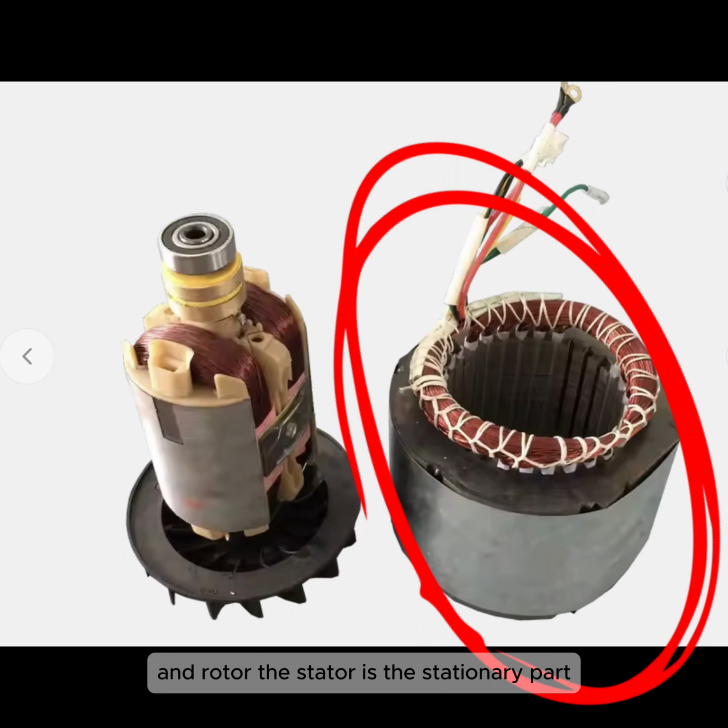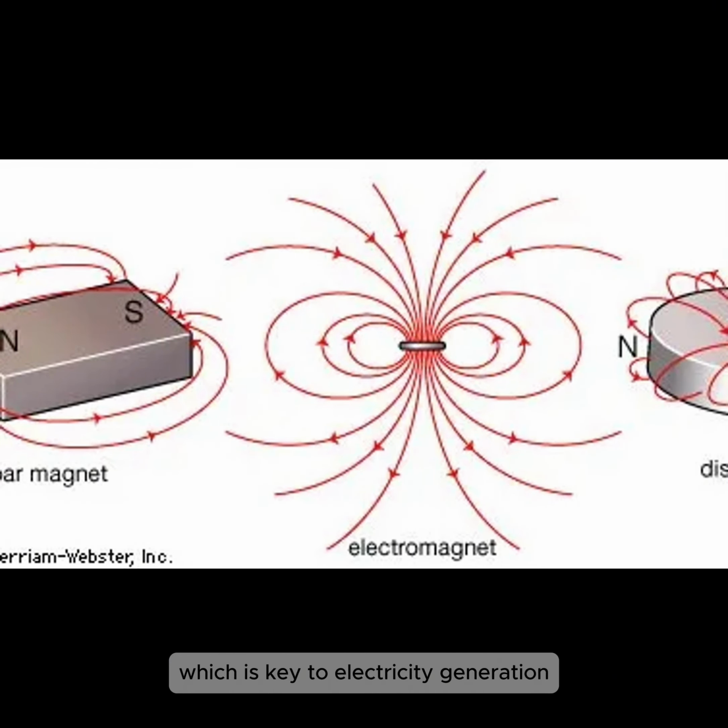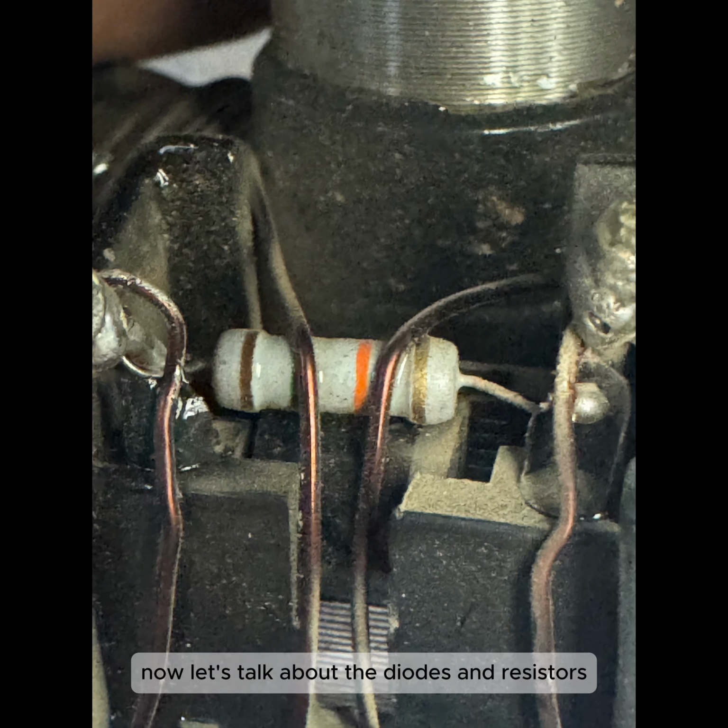The stator is the stationary part, while the rotor spins inside the stator, creating a magnetic field, which is key to electricity generation. Now, let's talk about the diodes and resistors. In a brushless generator like the Total TB18001, diodes are used to convert the AC current generated in the rotor into DC current. This is essential because the rotor generates AC, but the generator needs a steady DC supply to create a constant magnetic field.